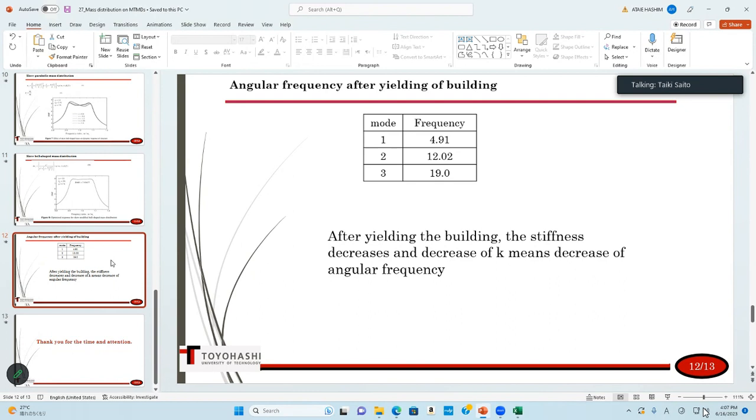Yeah, it's a good idea to put multiple TMDs. One is for the elastic range, another one is tuned for the inelastic range. Yes, but the model has to be a frame model, not a lumped mass model. And also, have you checked why the lumped mass model doesn't work for wind load?